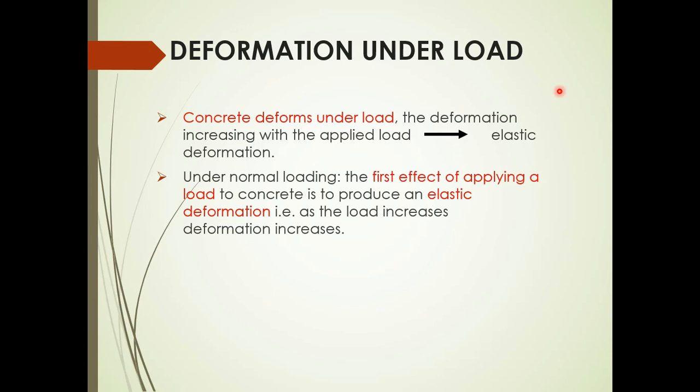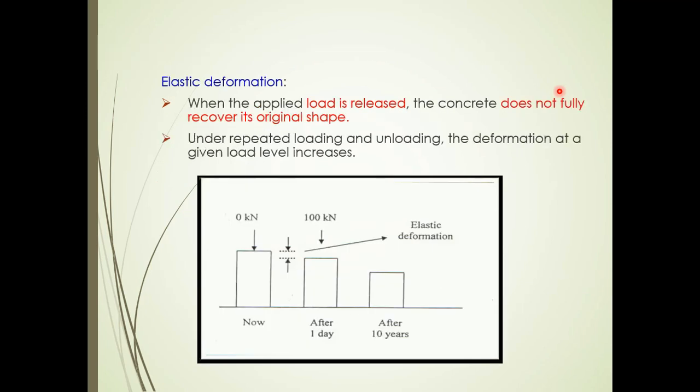So the last one is the deformation under load. Concrete will deform under load. Deformation increases with the applied load, which is what we call elastic deformation. So under normal loading, the first effect of applying a load to concrete is to produce elastic deformation. As the load increases, deformation will also increase. It is linear. When we increase the load, the deformation will increase.